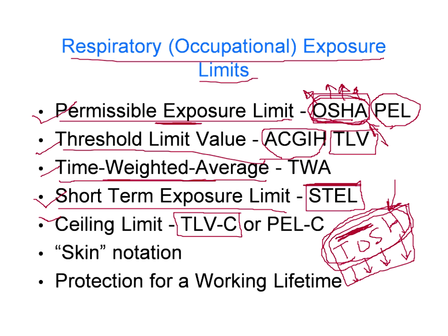Okay, and next is short-term exposure limit, STEL. This is not steel. This is still. Don't pronounce it like that. It is STEL, called short-term exposure limit. A worker can work only for a short period in the area. Afterwards he will get respiratory problems.